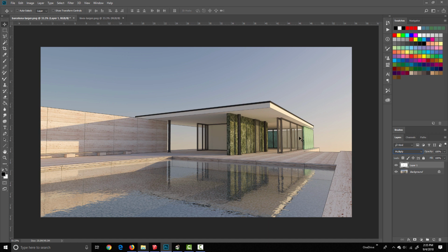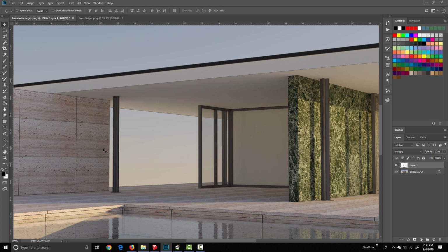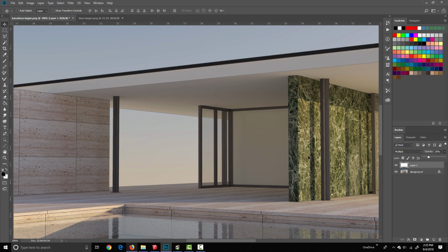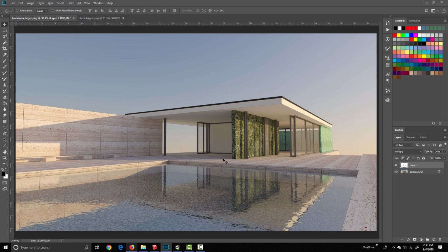Now, maybe it's a little bit too heavy. I would probably want to tone it down to something like 32 seems pretty good. I just want a subtle accent to sort of emphasize some of the edges, and this does look a lot better than it did in the previous version. But if you wanted a heavier line weight, you could use that all the way up at 100 or somewhere in the 60 to 80 range. But I'll leave it down here, zoom back out, and that's it. We have our finished line overlay.